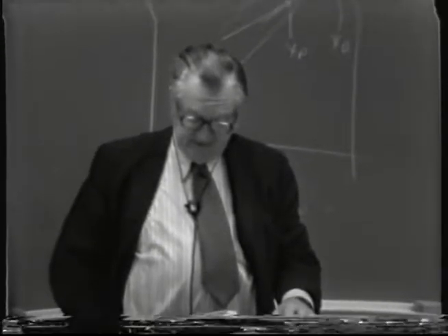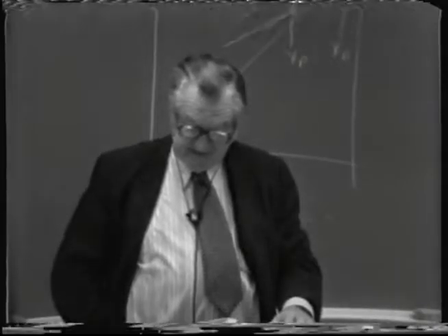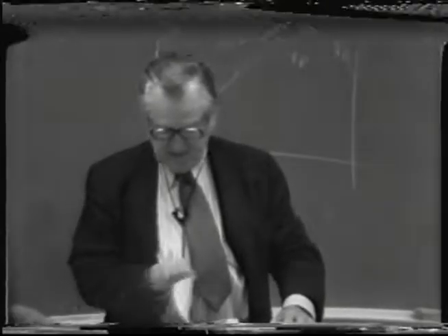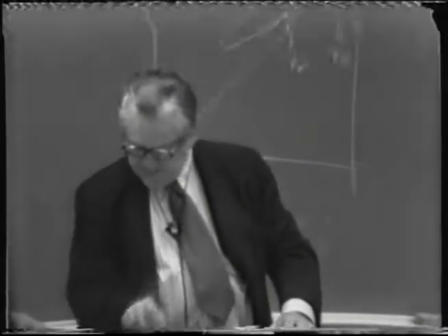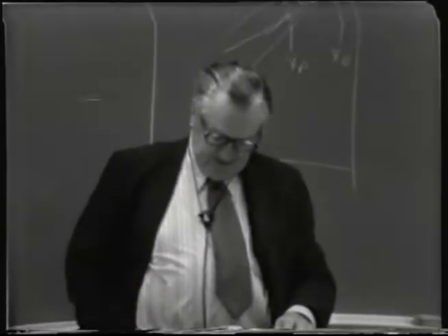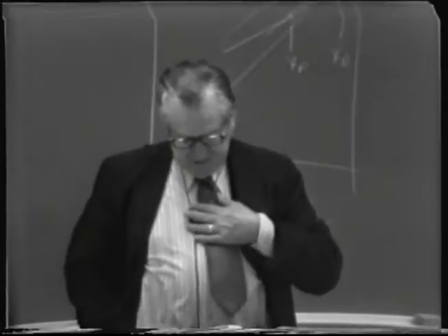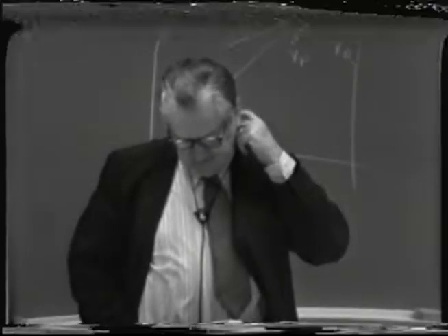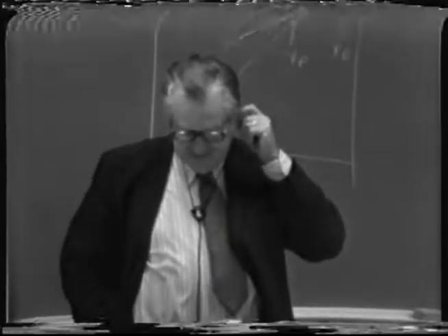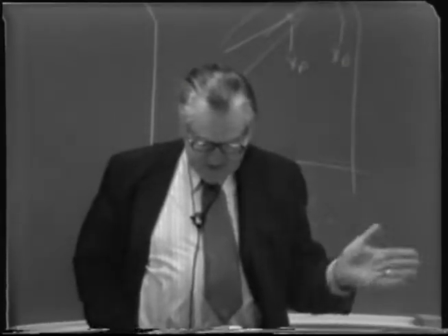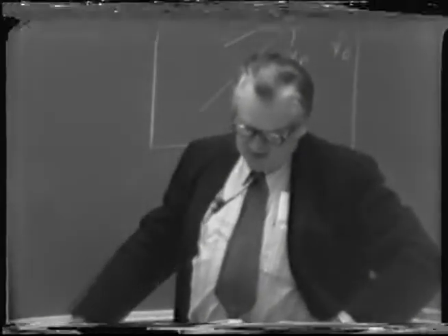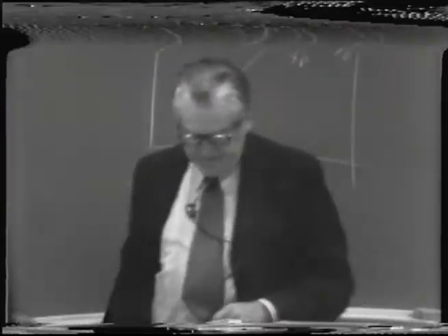So in other words, we'd have, very simply, if we have 14 ideal plates required in the rectifying section, I think before we said 13 plus, wasn't it? Or about 14 ideal plates. And assuming an average overall efficiency of 8/10 or 80%, comes out to be 17 or 18 actual plates. And of course the height then would be, if we have 12-inch plate spacing, simply 1 foot per plate, or in other words 18 feet.